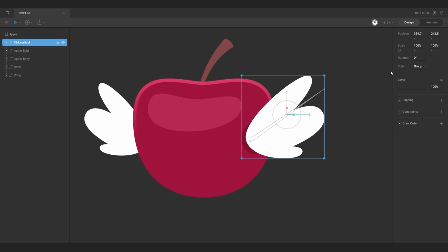Now, change the style of the group to target, and I want to move this target to this position, in the center of rotation. Use the Y key to activate freezing and move here. And you can see here it's difficult to know what this position is.